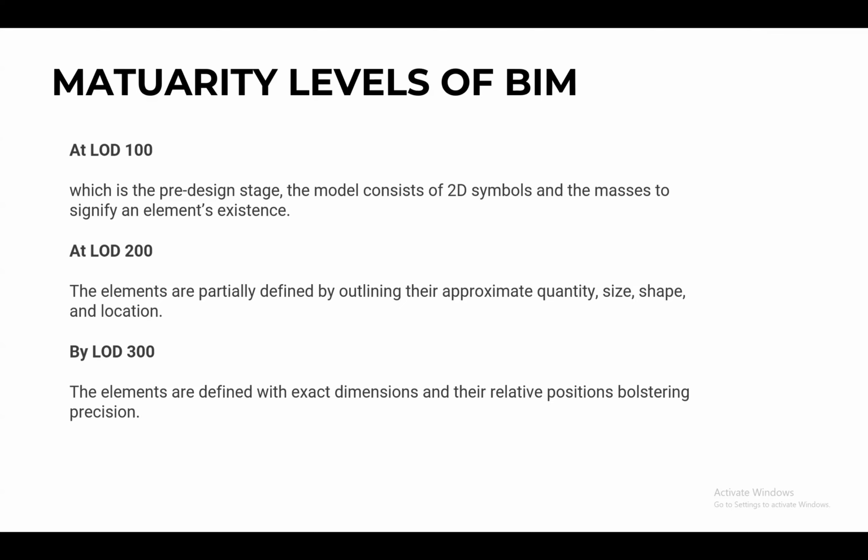But the LOD 300 model is a comprehensive model, and you can get exact dimensions. Basically, you can develop some cost plans based on LOD 100 and 200. As pre-contract quantity surveyors, we have to provide cost plans for CD, concept design 50 drawings, and concept design 100 drawings. So LOD 200 and 100 come under concept design cost plans.